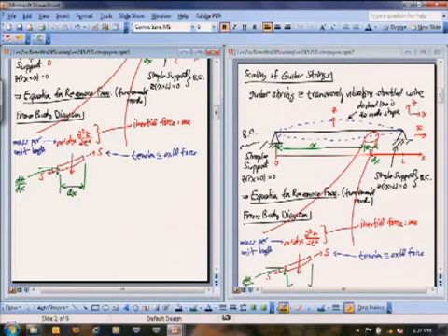Okay? And I can do the same thing on the other side. So I'm looking at this. I want the force going up in that direction, and the force going up in that direction is going to be this S times whatever that angle is. But now that angle is a little bit different. Right? That angle is going to be the angle that I had on this side, but modified by any angular change that occurred across this differential element. And I can model that by, on the left side it was dz/dx, but now I'm going to model that by the second derivative of z with respect to x times the length of that differential element dx.